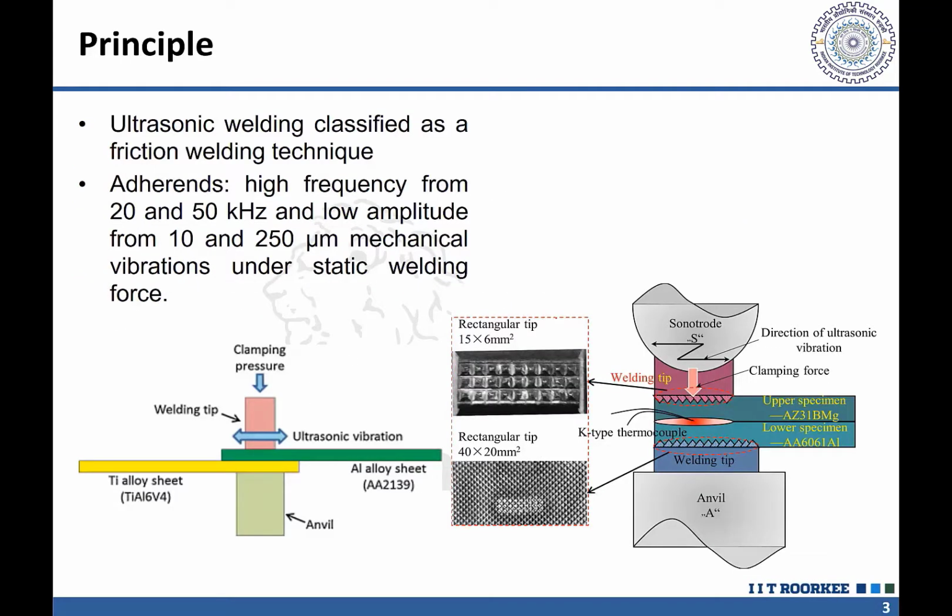So here, if we see the working principle, this process basically depends on the frictional heat generated at the interface, and this interfacial frictional heat generation is realized by providing high frequency, low amplitude mechanical vibrations.